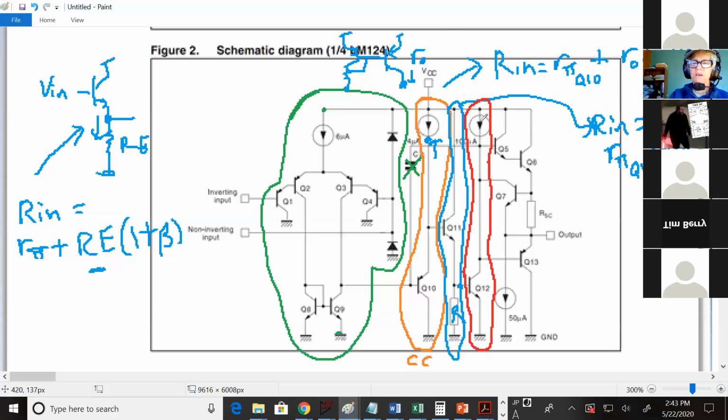And this is written as a current mirror. What flavor of common emitter amplifier is that? Active load? Active load, yes. So when you see a current mirror up top, that just means you have a PNP up there, that's what an active load is. So this is a common emitter with an active load.